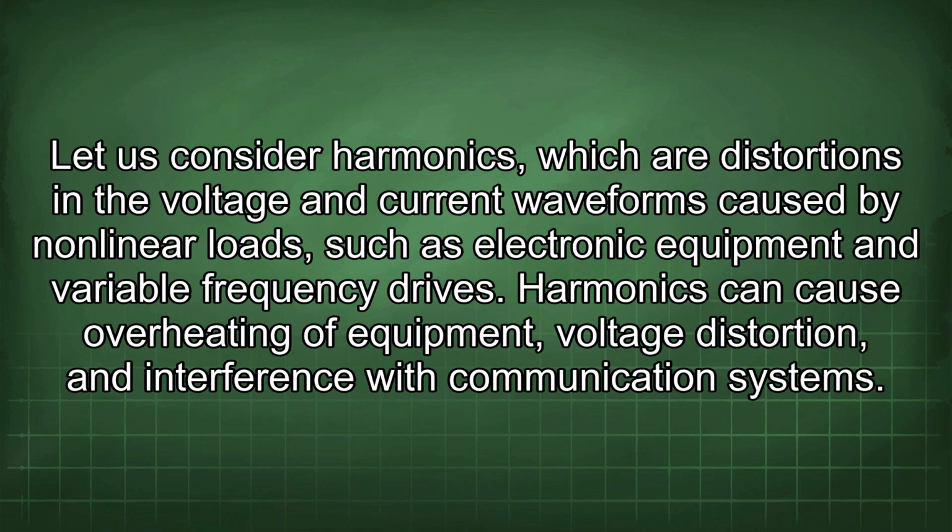Let us consider harmonics, which are distortions in the voltage and current waveforms caused by nonlinear loads, such as electronic equipment and variable frequency drives. Harmonics can cause overheating of equipment, voltage distortion, and interference with communication systems.